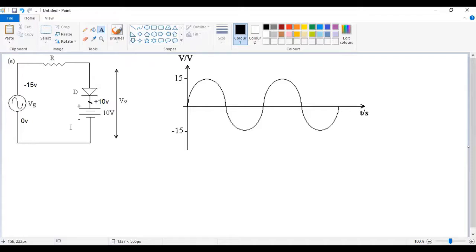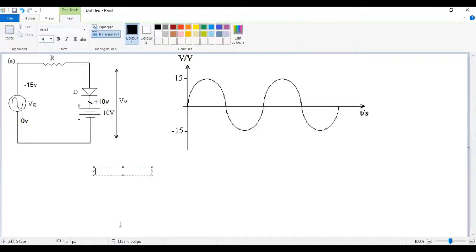Now this becomes very simple. Once you have set the terminal of one of your diodes, then it's very simple. This diode here is forward biased if this node here is above 10 volts, because this is the anode and this is the cathode. So as long as this terminal is above 10 volts, your diode is forward biased. So let me write this down. What we've concluded is your diode is forward biased when your voltage is above 10 volts.